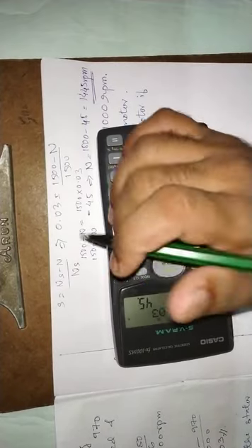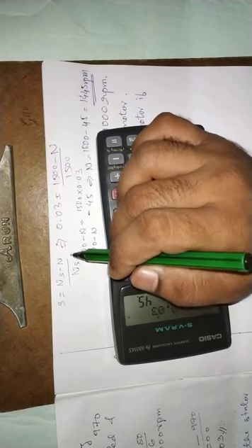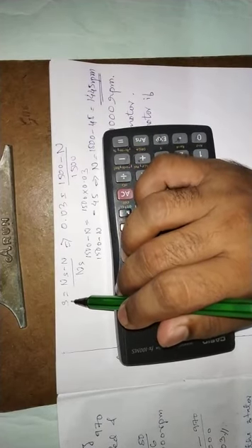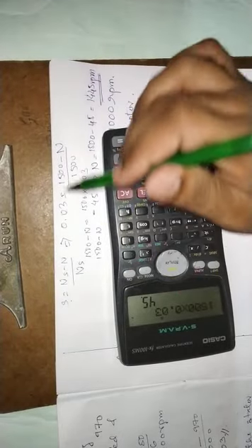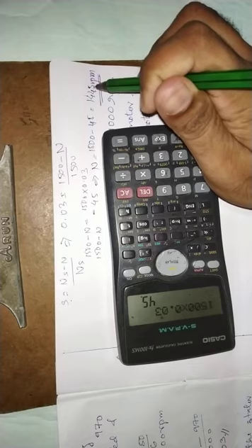So this is how we have calculated the value of Ns as 1500 rpm, and we had the value of s as 0.03 by the calculation of f' = sf. So by substituting the value of s and Ns, we have got the value of N as 1445 rpm.